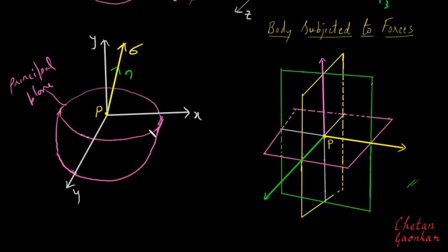We'll assume that there is a plane whose outward normal is n, and therefore its direction cosines with respect to x, y and z directions will be nx, ny and nz. And we'll assume that the stress acting on this plane is wholly normal, and there is no shear stress on this plane. This sigma we can call the normal stress vector acting on this plane. So the resultant stress vector has to pass through this normal itself, because there is no shear stress as such.